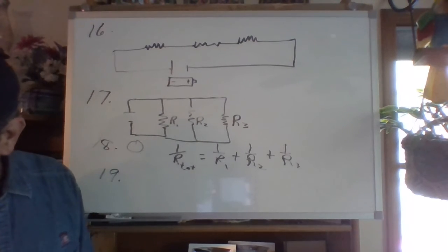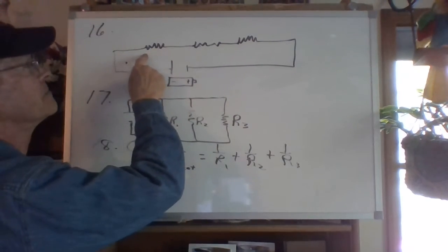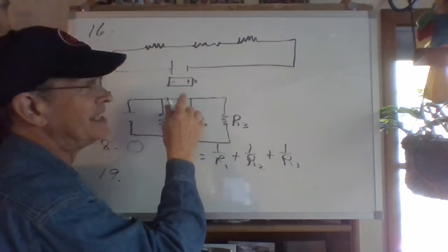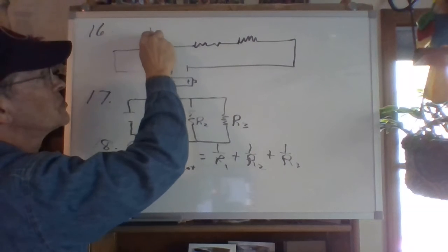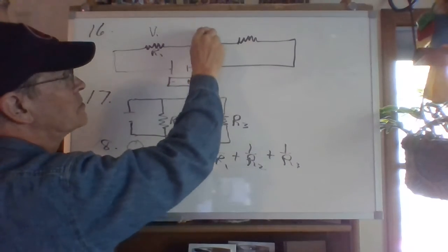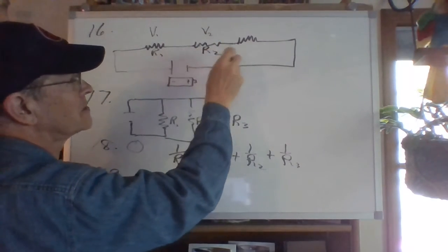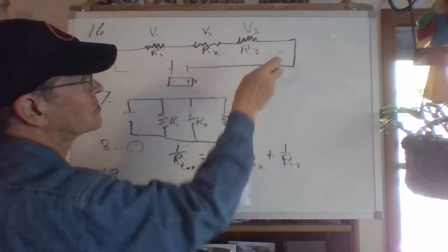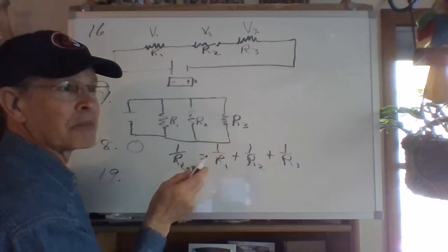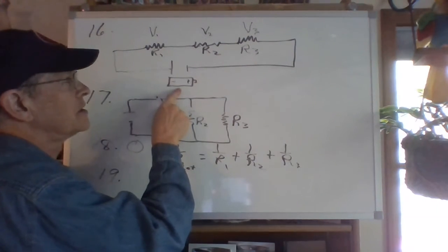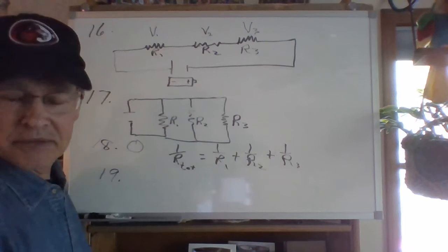What about the second rule? The sum of all the voltage changes that occur in a circuit must be... Well, we kind of already mentioned it. It makes sense. It's the law of conservation of energy in disguise. If you take this voltage drop at the first resistor, and this voltage drop at the second resistor, and this voltage drop at the third resistor, all of those voltage drops can't be more or less than the voltage that was applied originally. So the total voltage changes have to be, again, zero.